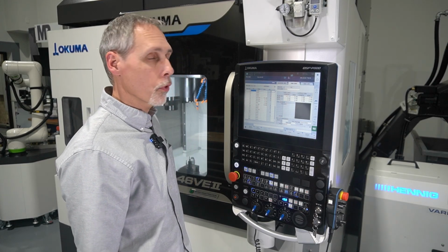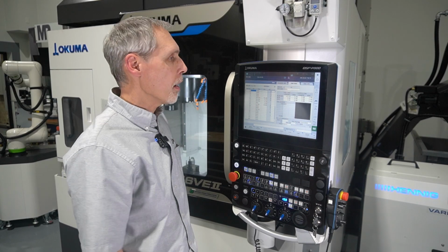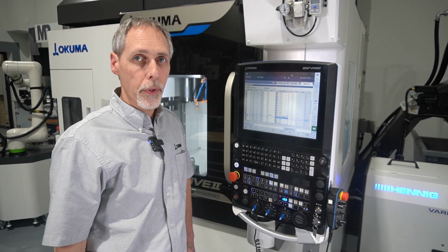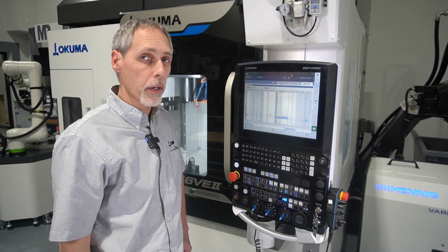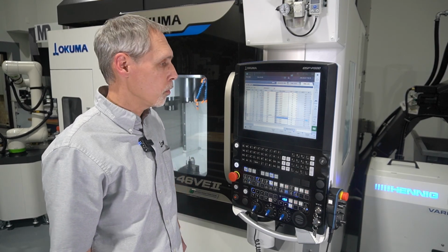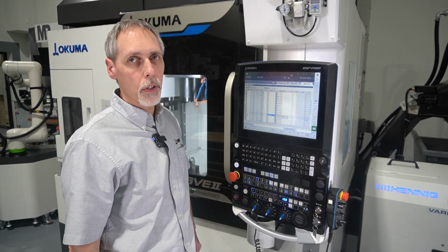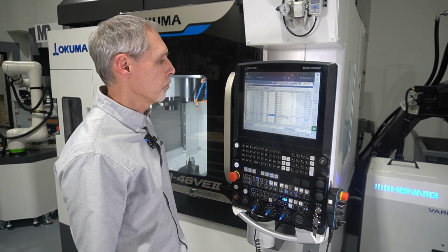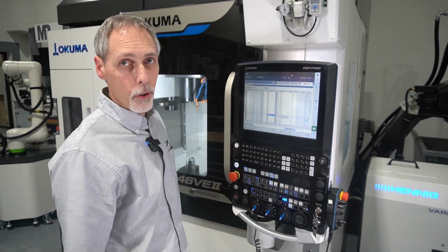And there's one more thing I want to show you. Once your tools are all expired, we need to reset them. So the operator has to go change the tool out if it's broken or if it's expired based on the time or the count. We need to reset these flags. If I try to run a program with a tool that's flagged, we'll get an alarm. So we need to reset the flag and update our counters.